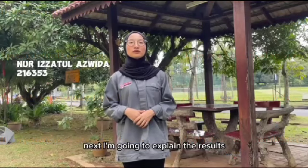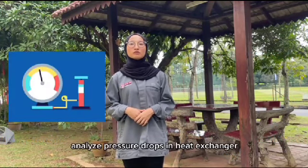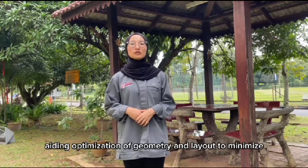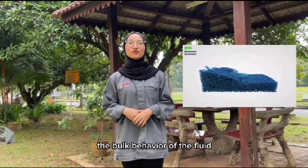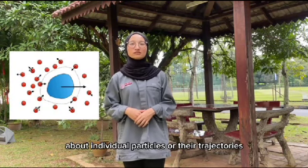Next, I'm going to explain the results by using Eulerian and Lagrangian methods. Eulerian simulations analyze pressure drops in the heat exchanger, aiding optimization of geometry and layout to minimize energy losses. As for discussion, Eulerian simulations are suitable for understanding the bulk behavior of the fluid but may not provide detailed information about individual particles or their trajectories.